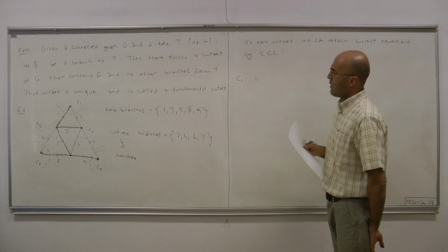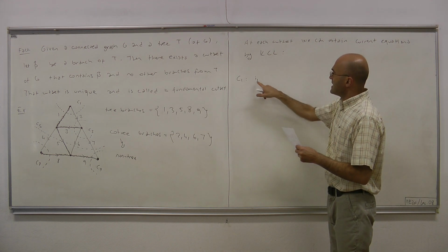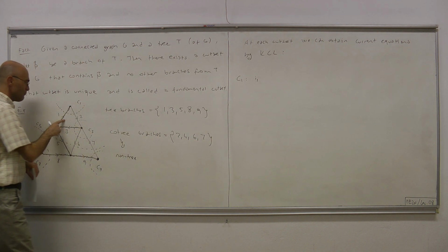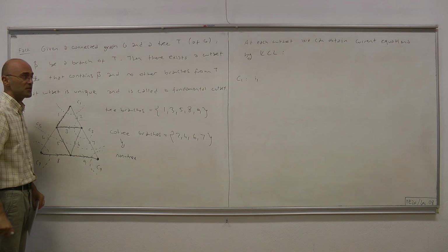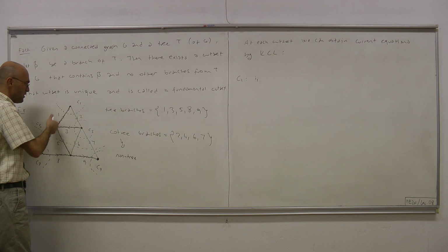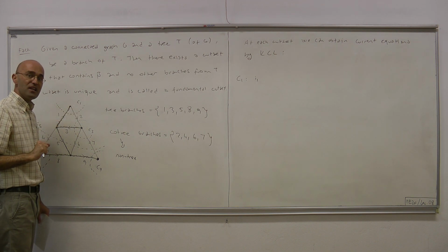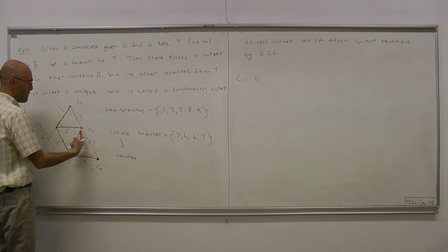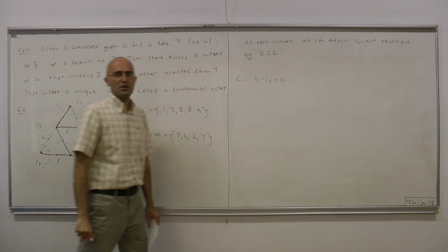I1 equals I2, but let's write it following the convention that the current that belongs to the tree branch which makes that particular cutset, let's consider that as our reference direction of that current. So the reference direction is, let's say, incoming, then we consider all the currents as incoming, and the sum of all those currents must equal 0. So I1 is incoming, and minus I2 is incoming, and that all equals 0.